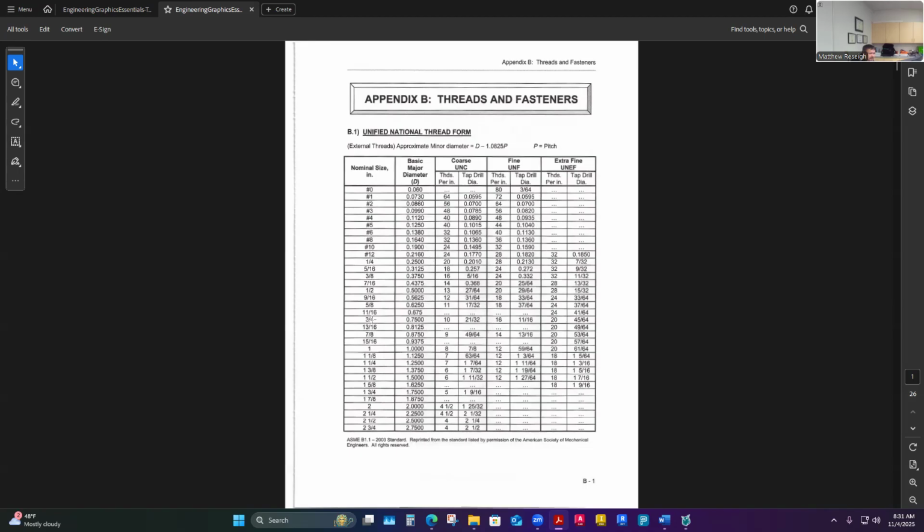And this is probably a major diameter that we're seeing here when we see this size. If you guys have used fasteners, if it's a bolt, you realize that for a half-inch bolt it's not a half-inch wrench that I need to undo it, right? Because there's a size difference from the head to the actual shaft of the bolt. So it gets confusing to know what size goes with what. We'll learn a little bit about that. The more you use that stuff, the more you start to memorize which tool goes with which size of bolt, and how to identify them.